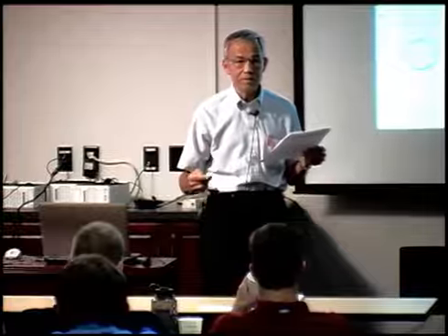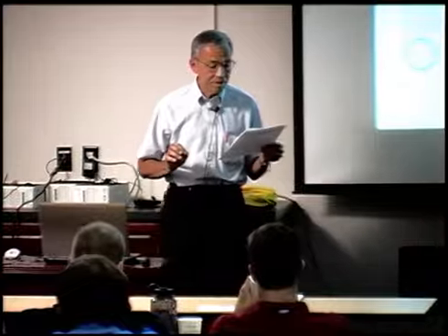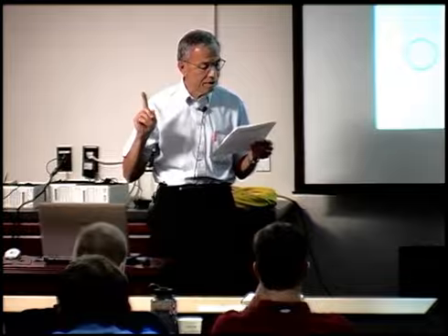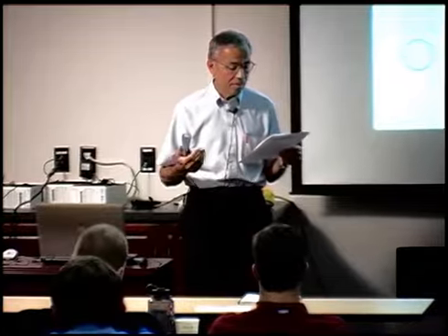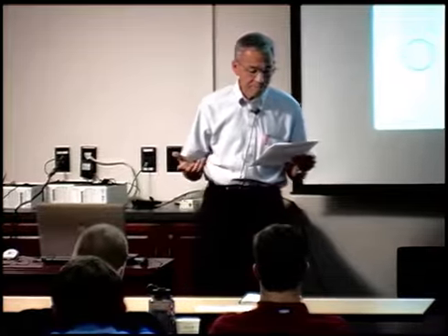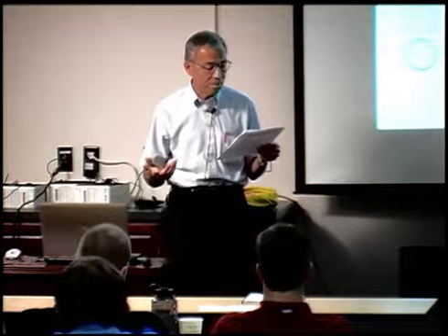In other words, they drove the pile about halfway and they had bearing. There were cases, though. There was one case where they had to do a retap, 1 out of 14 substructure units. There were 3 cases where they had to go to 90% of the pile length before they got bearing.